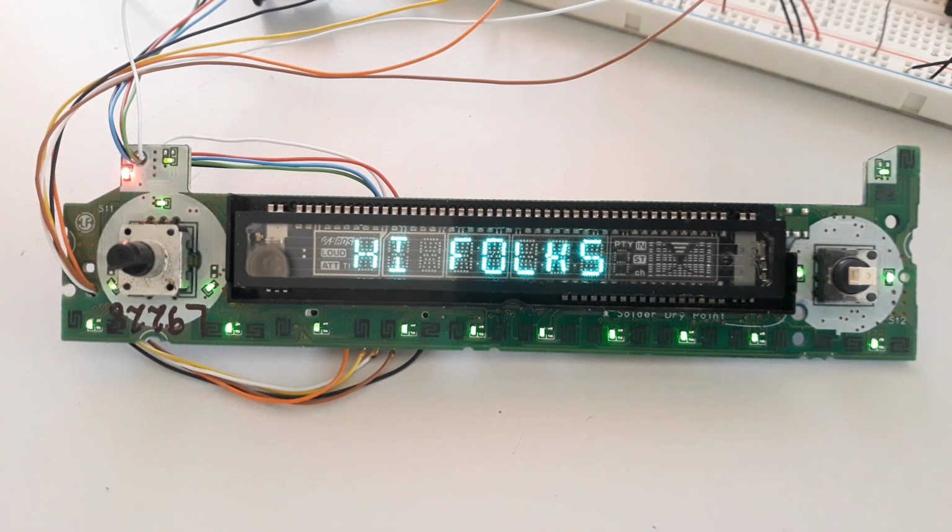I like the fact that the driver, when started by default, remains at a low dimmer value, which prevents any visualization. For this reason, the first 3 lines of the loop are to set it to maximum, so as not to be misled into thinking the panel does not work, when it is just a lack of brightness.